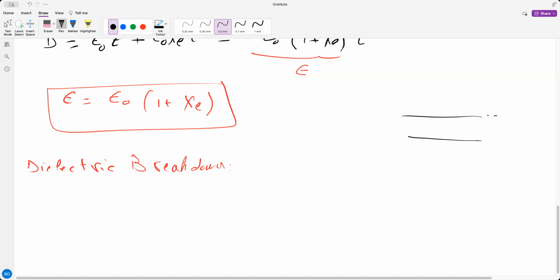This is a capacitor, you have a positive, for example, negative, and you have a dielectric here, right? So now, if you apply a very, very high voltage to the capacitor, what happens is that this dielectric will start having electrons extracted, and this means it's like you are creating a short circuit between the positive and negative charge, and then your capacitor blows up.